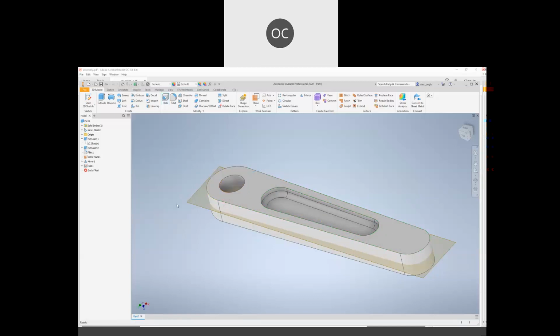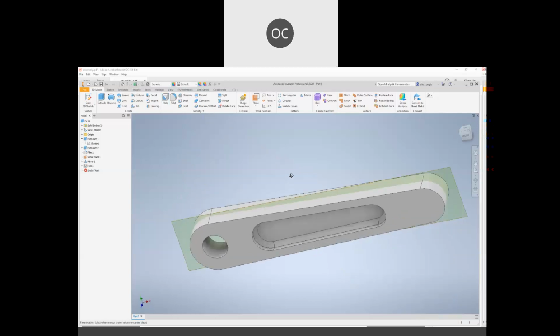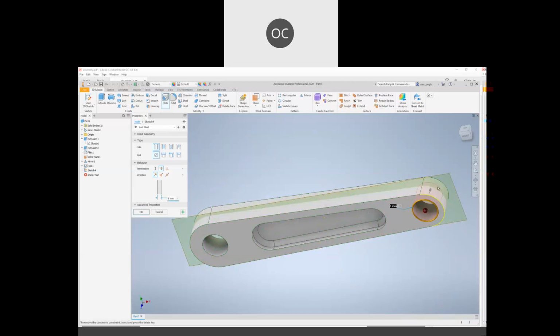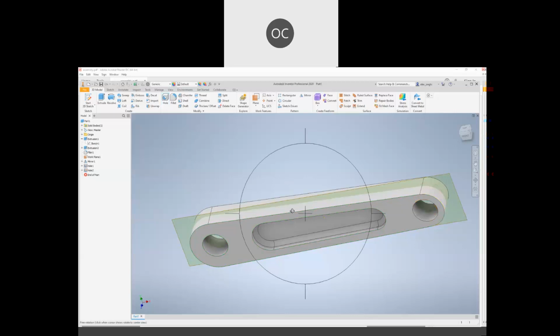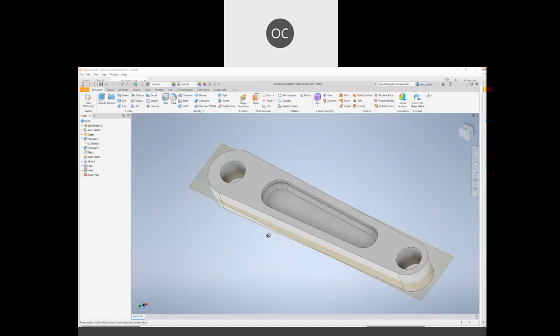The second holes, you are going to repeat the same step here that you have. Okay. So holes again, surface, and then you have reference. Okay. So the arch, you can click on the arch also to turn as the concentric reference. The diameter will be also 6. Okay. So you should have this form here.